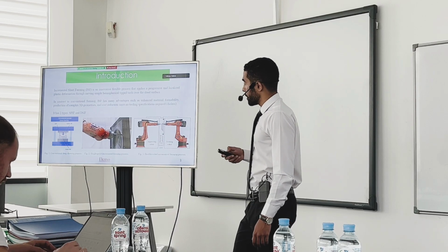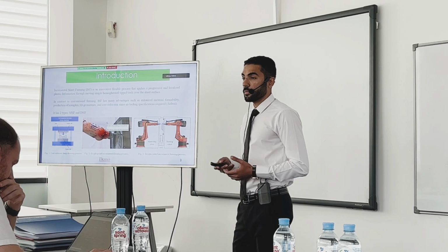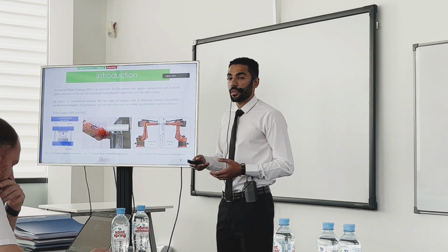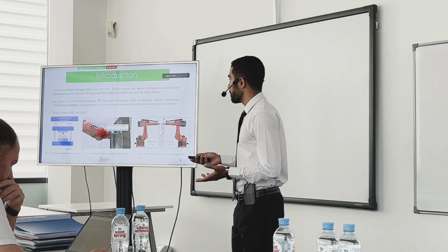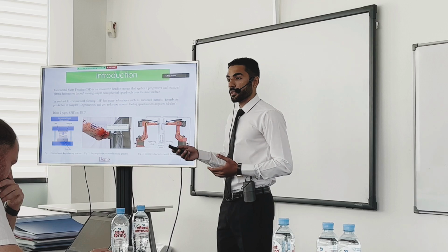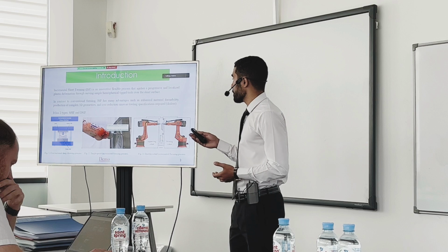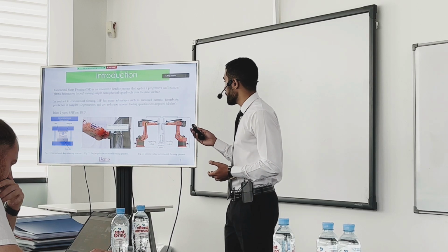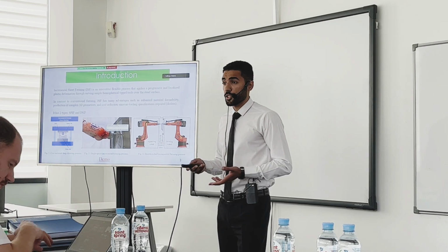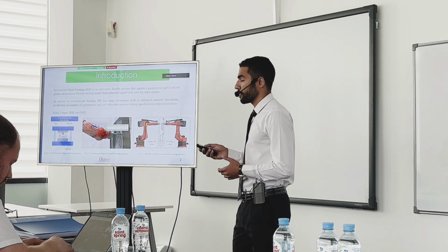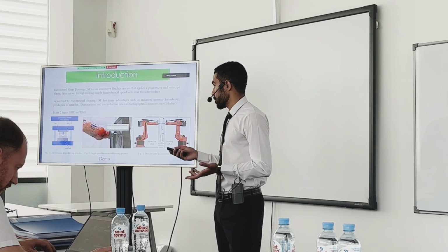So to start, basically what is the incremental sheet forming? Incremental sheet forming is an innovative flexible process in which you apply progressive and localized plastic deformation in a sheet surface to make a certain shape. In contrast to the conventional deep drawing methods like stamping or drawing, this method has a lot of advantages such as the enhanced material formability, the ability to produce complex 3D shapes, and the cost reduction, because basically you don't need to design a die for each shape.